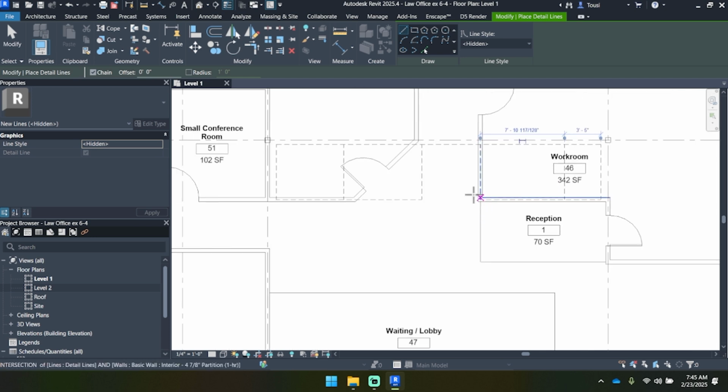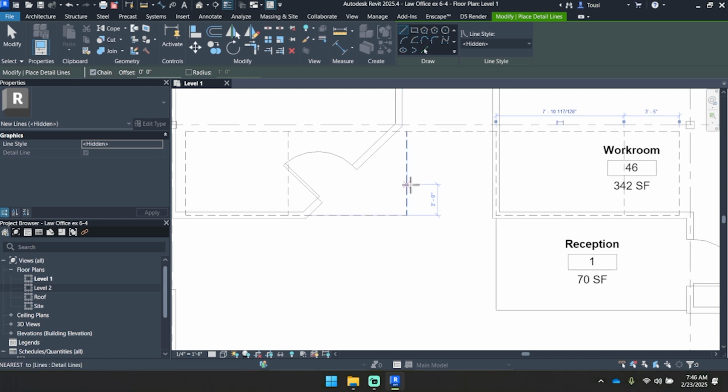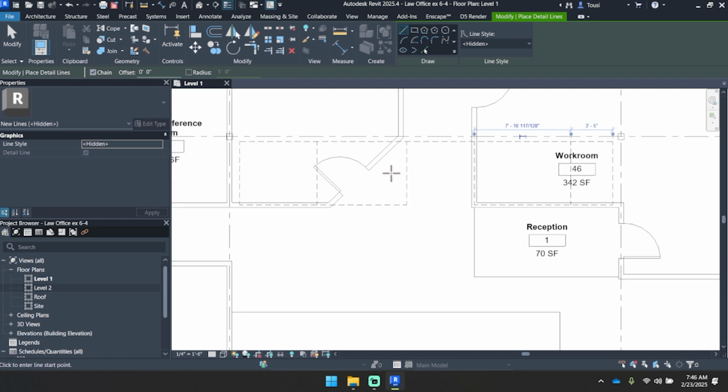And then, I know I just said that drawing concurrent lines is not the typical way to do it, but this is going to be a condition where we actually do want to break up some line pieces so that we can hit midpoints of certain lines. So for example, with this project, this line right here, we're going to eventually need to know the center of it so that we can draw the center of the stairs up it.